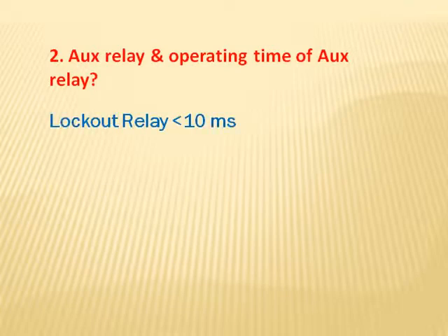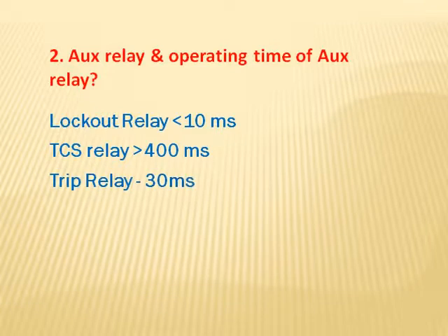Operating time of lockout relay is less than 10 milliseconds. Operating time of TCS relay is greater than 400 milliseconds. Operating time of trip relay is 30 milliseconds.